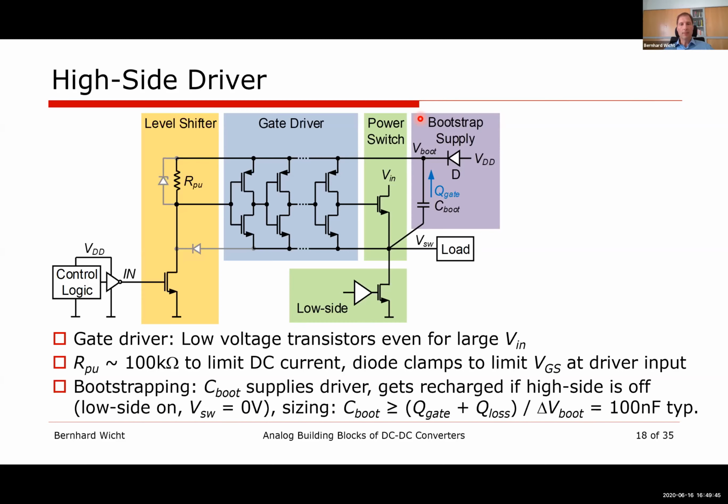Yeah, thanks for bringing this up. Of course, I could talk for 5 hours. I didn't want to do that, so I had to take out some details. That's a good point. What I intended here is to focus on integrated power stages, and integrated power stages make our life a little bit easier in terms of parasitics. The inductances in the power path that you're referring to would be here in the power path, right? We have inductance here at all the connections, drain, source, and also at the low side and towards the load.